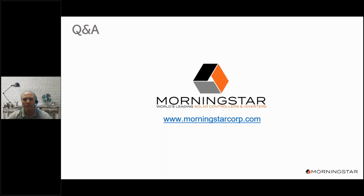Although the Sun Saver Duo can be custom programmed by PC, it does not have all the settings you really need for lithium, so we caution against trying that. The ones that can be used with lithiums are the ones that can be custom programmed by PC. We have our MSView software, free software, and there are various connection methods depending upon which controller you're using.